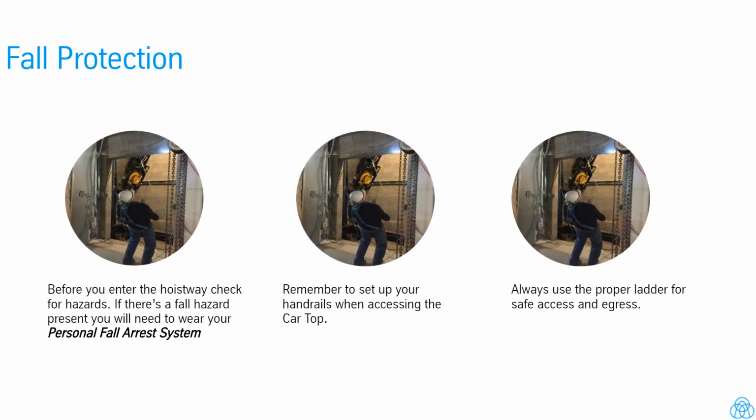Fall protection. Before you enter the hoistway, check for hazards. If there's a fall hazard present, you will need to wear your personal fall arrest system. Remember to set up your handrails when accessing the car top. Always use the proper ladder for safe access and egress.